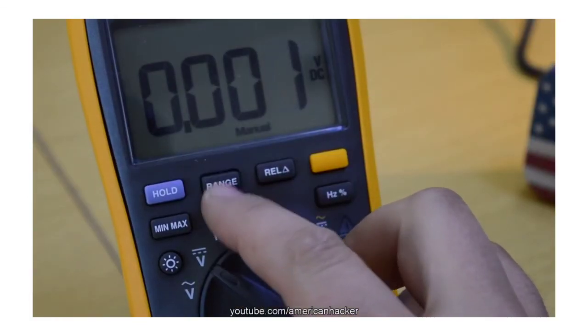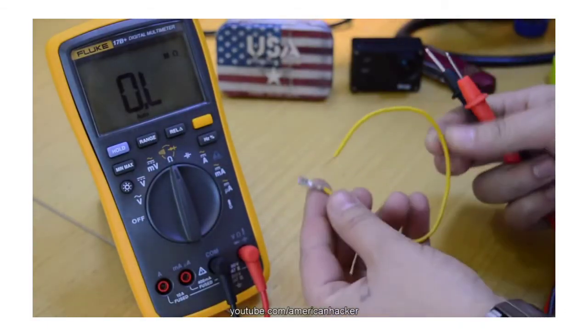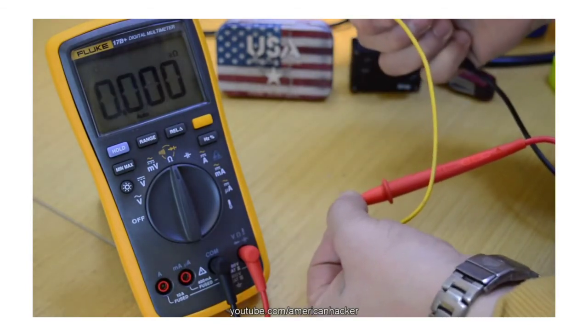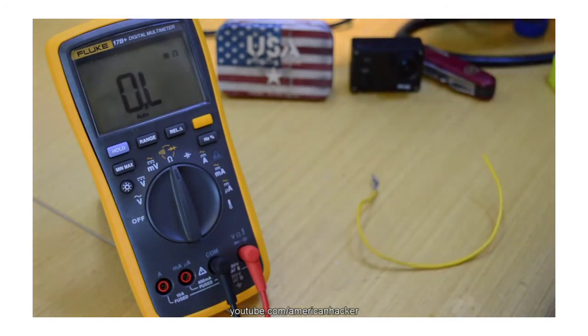Measuring resistance is easy, just set the dial to the resistance settings. Measuring continuity means checking if there is a good connection between any 2 points in the circuit or wire, and whenever there is almost zero resistance between 2 points, the multimeter will beep.